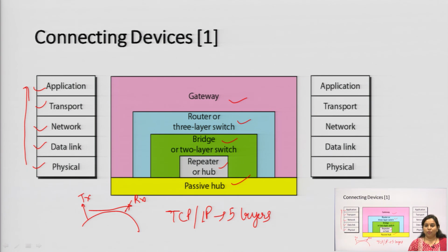Secondly, it is going to maintain the strength of the signal, that is definitely the quality, and also it is going to repeat the same signal that has been received at its input. So, repeaters are there, and generally approximately after 50 kilometers we have to use a repeater. So, this is the function of the repeater.